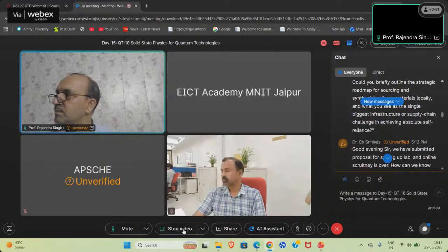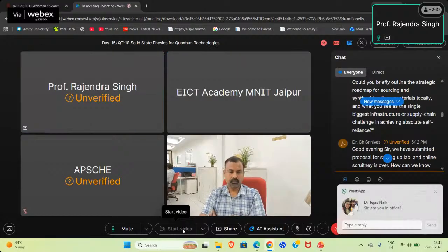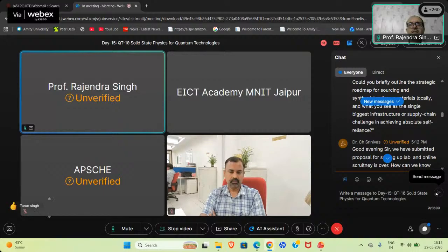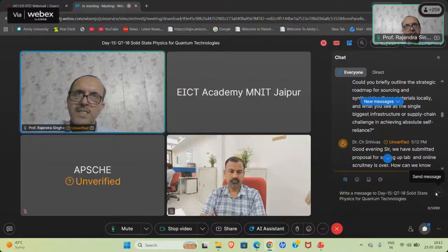Yeah, so all these semiconductor devices definitely have their lifetime. LEDs, as you know, also have quantum wells. The light emission in an LED comes from a quantum well, and all of us know LEDs have a certain lifetime. Each device, each material has a certain lifetime, and typically LEDs have a lifetime of 10,000 hours. For these quantum devices, right now I don't have the numbers, but definitely it shall be a few thousands of hours, because ultimately it has to be used in a quantum network, and in a quantum network it has to work continuously for years. So it shall have a lifespan of at least, let us say, a few years to start with.